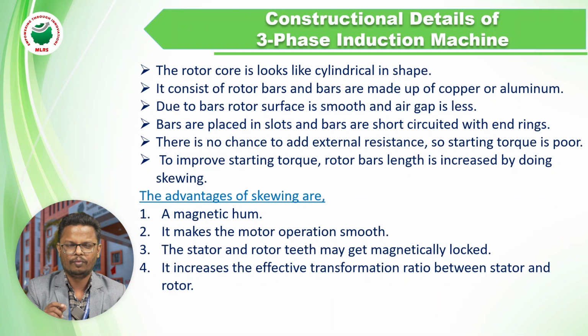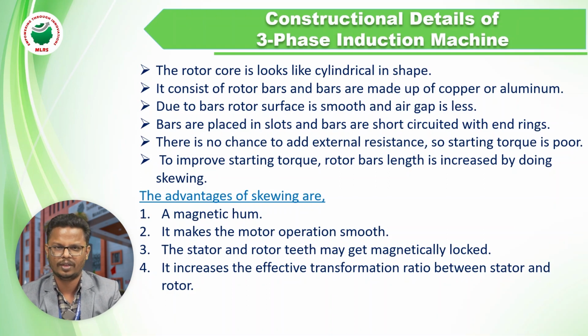So here we are making a skewing. We place the bars in an inclined position with some angle theta. That inclination makes the bar's length increase, so the resistance will increase, and the starting torque also increases. This process is called skewing.